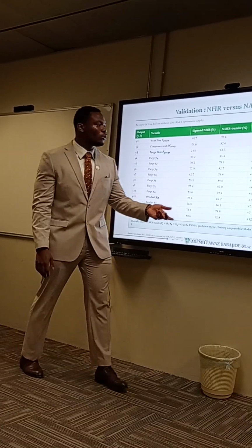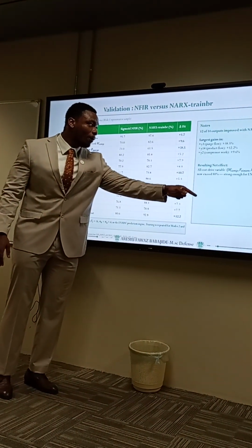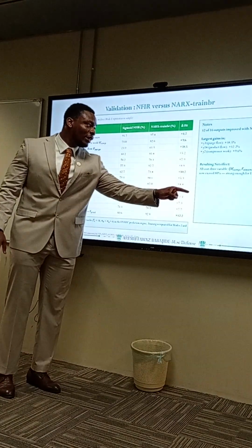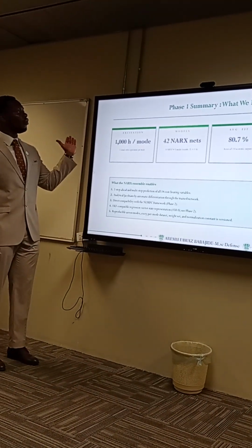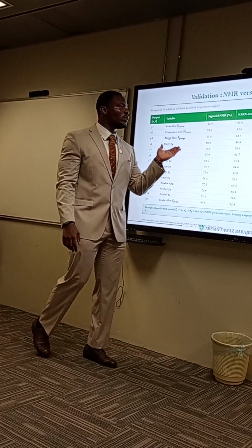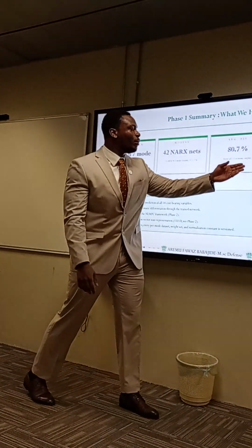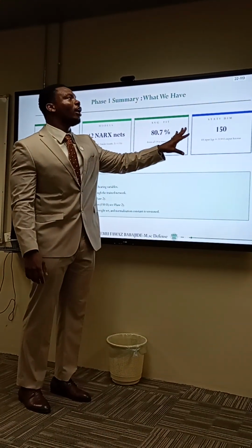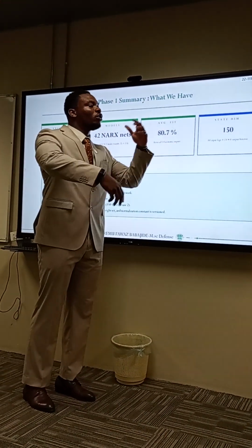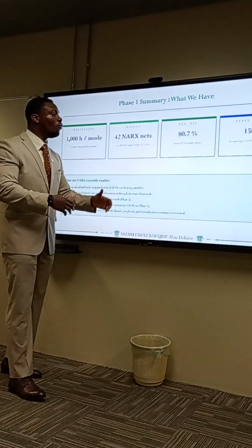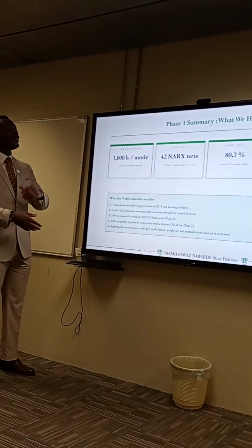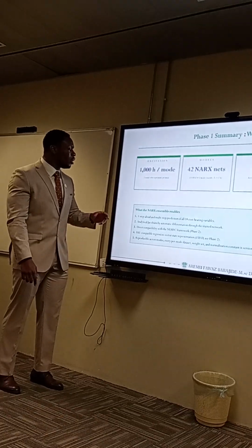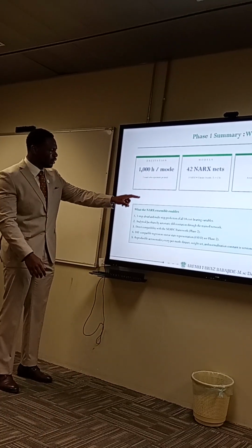Of course, we're able to capture all cost variables, basically the compressor work, the flow of steam, the flow of the purge over time, and then the production. And of course, after running this, this is basically the summary of what we did. Basically, you have about 16 inputs here. It's a NARX model because we have to inject and shift inputs over time. So that's why we did it for the 14. It's a MISO model, so when you combine that, it's about 150 dimension models. So it's quite heavy on the network, if you ask me.